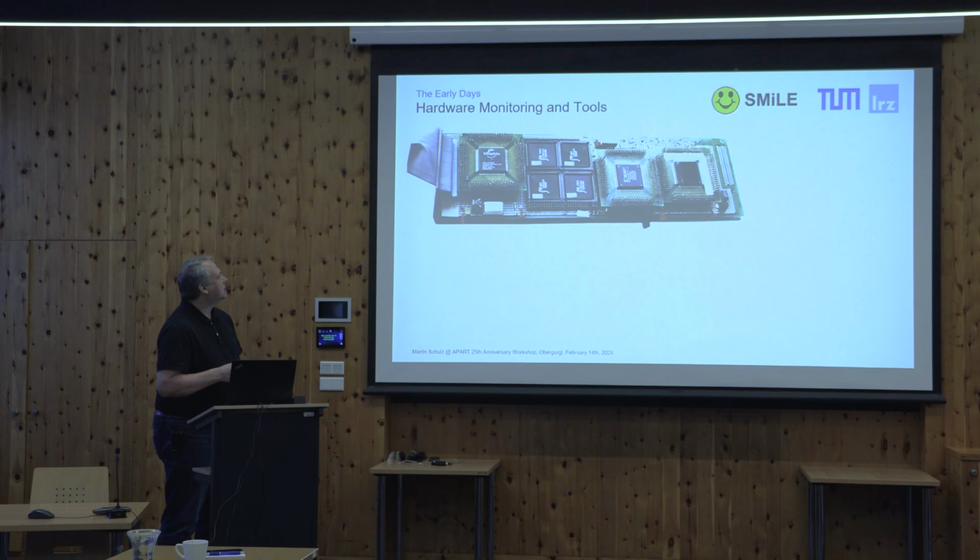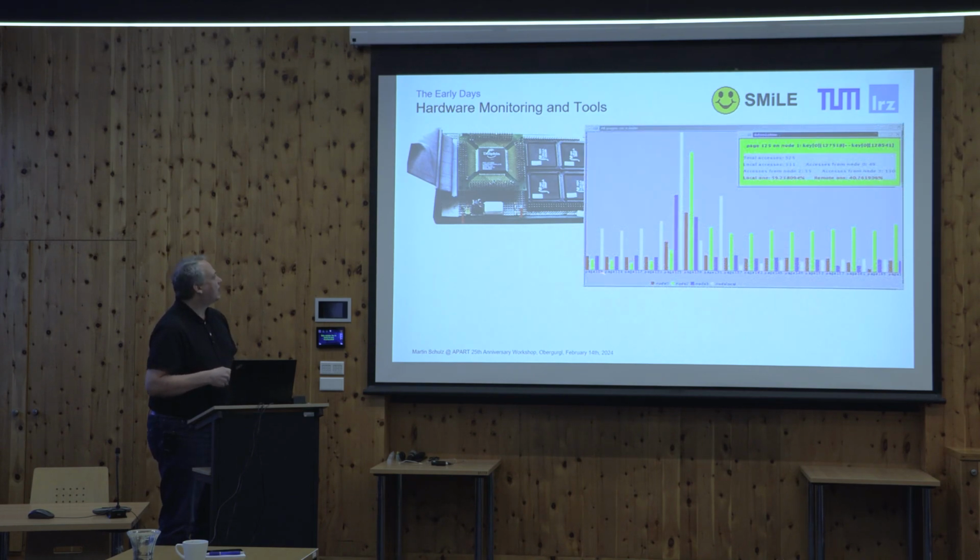And then building on top of that was a monitor adapter card, which was able to track all memory traffic. It was a shared memory card, so there was a lot of shared memory traffic going on, and we could track that and find out exactly what was going on in the traffic at that point. We were able to do graphs like this, where we could find out which pages were accessed by which nodes in the system, so we would know exactly how the NUMA distribution was in this distributed system.